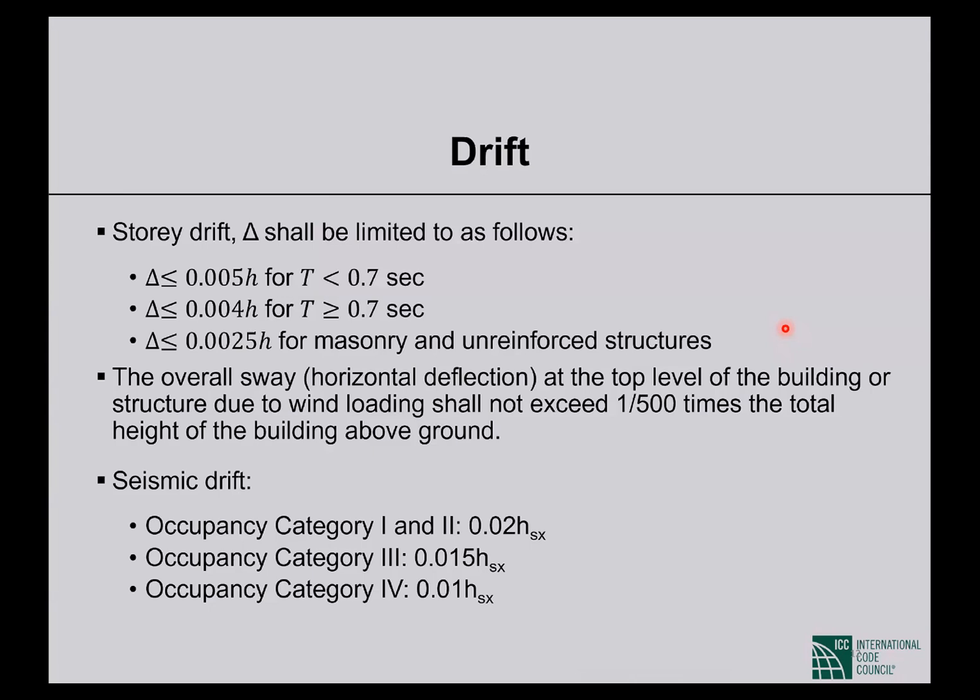So if you want to understand more about this, you have to study structural dynamics. So just know that every structure has its own period, and we can calculate that period. It mostly depends on the height of the structure. So if it is a tall structure, then the period is long. If it is a short structure, then the period is usually short.